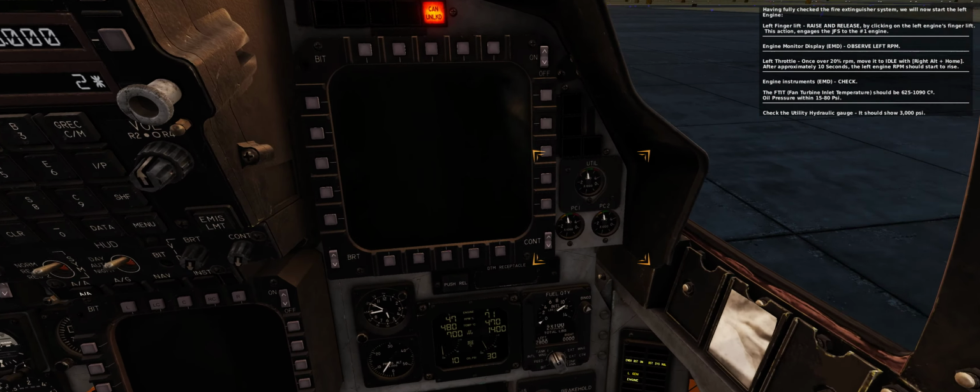The F-15E is equipped with the APG-70, which is a high-frequency pulse Doppler radar, capable of operating both in air-to-air and air-to-ground modes. In this standby mode, the radar will begin warming up, which takes around 3 minutes. After that time, it can be placed in full operation by turning this knob to on.